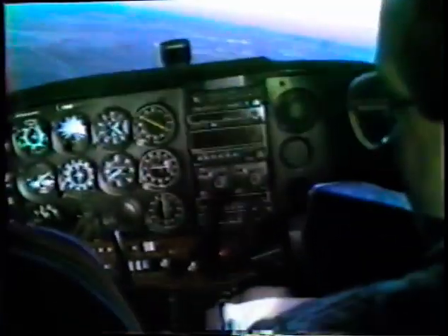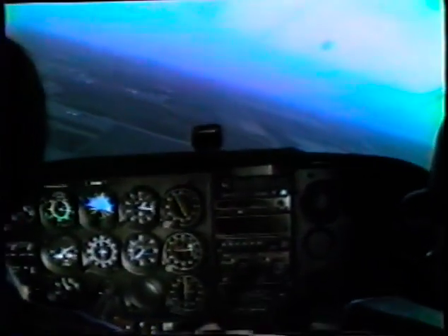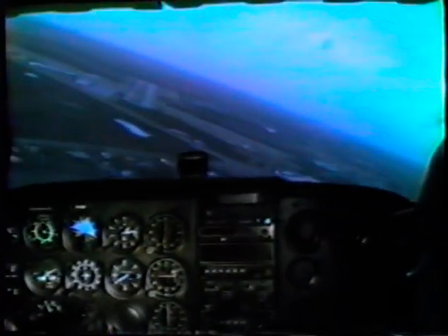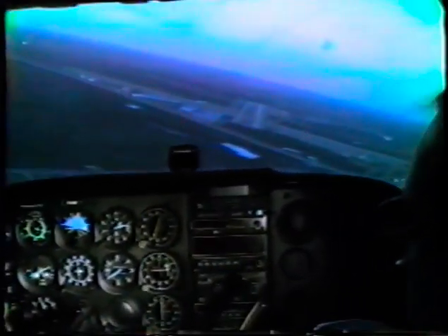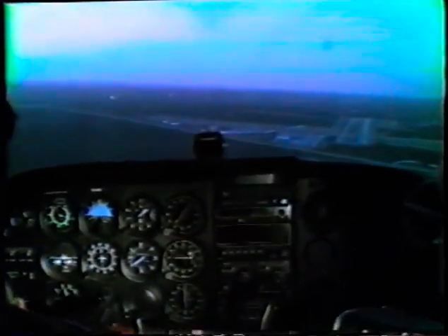At a field with no control zone, circling presents an additional problem. Below 700 feet AGL, you are in uncontrolled airspace where VFR minimums are 1 mile and clear of clouds. There just might be somebody in the pattern practicing touch and goes, and you are both legal. Broadcasting your position and intentions on Unicom is your only defense against this danger.